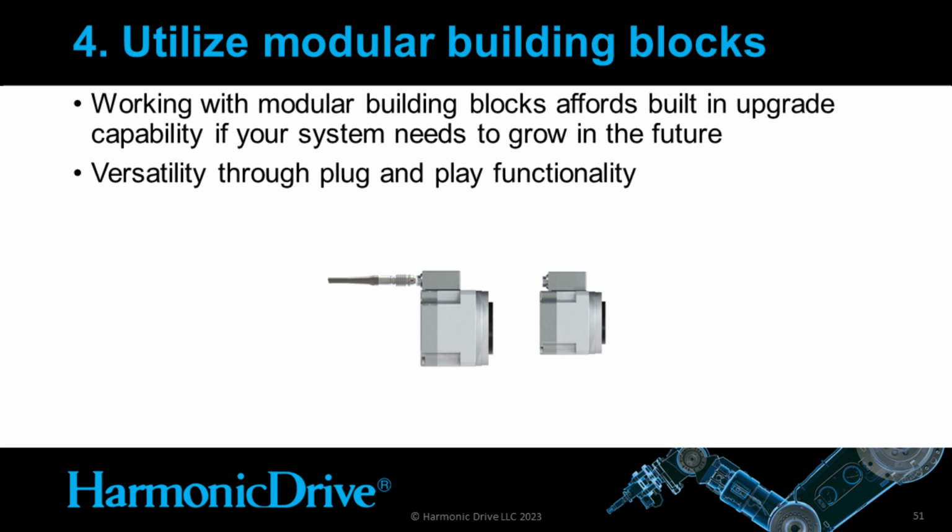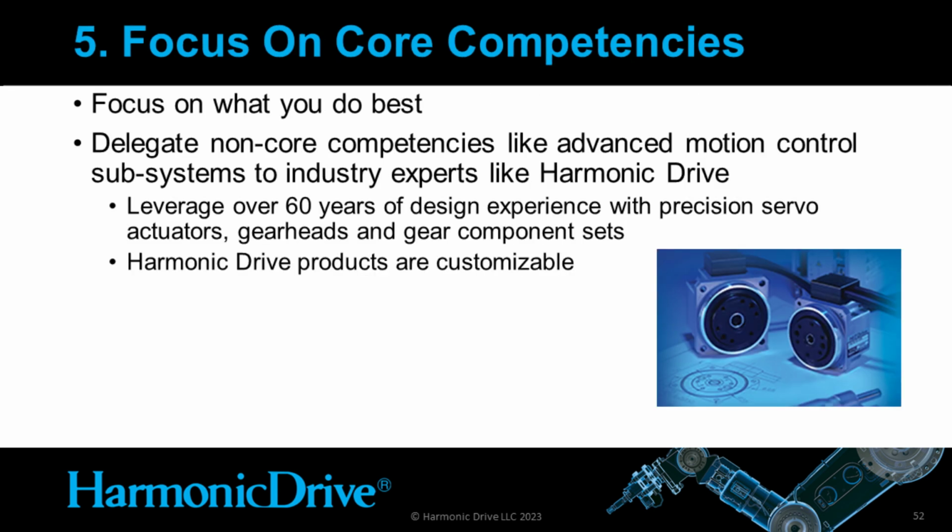The next tip I have is to utilize modular building blocks. What this means is to use things that you can switch out easily to buy yourself upgrade capability if your system needs to grow in the future, and versatility in case you calculated your torques wrong, or you need different gear ratios, or if you need a totally different size actuator to be placed into your system. So just like that, you can change out your axes.